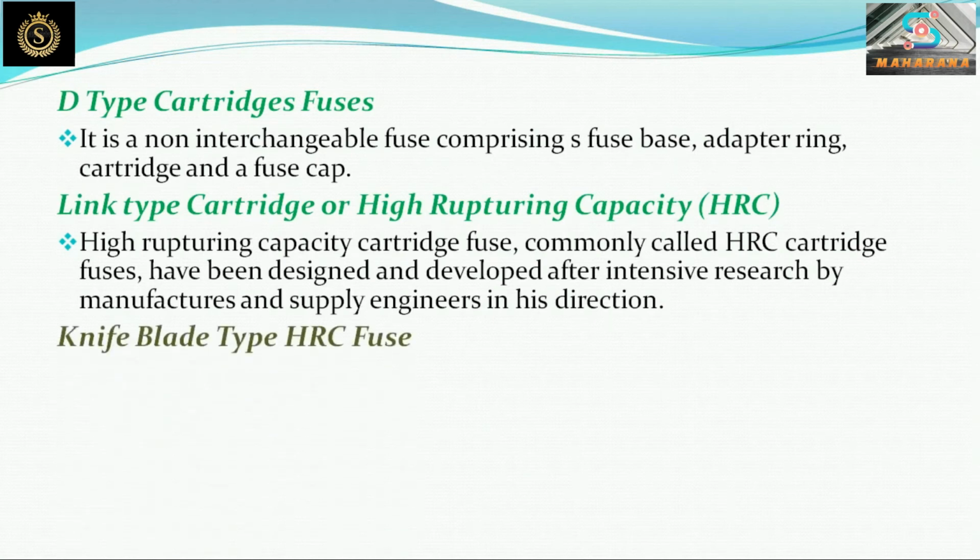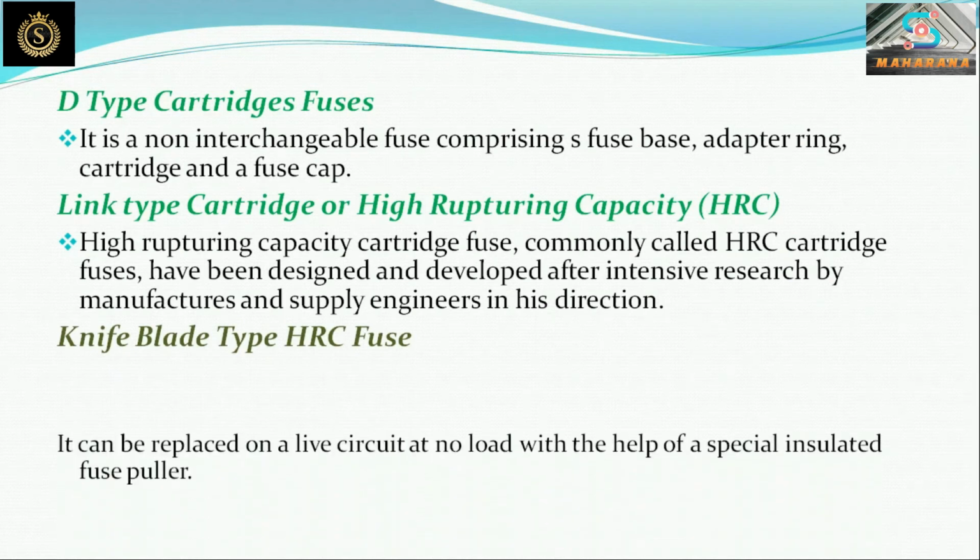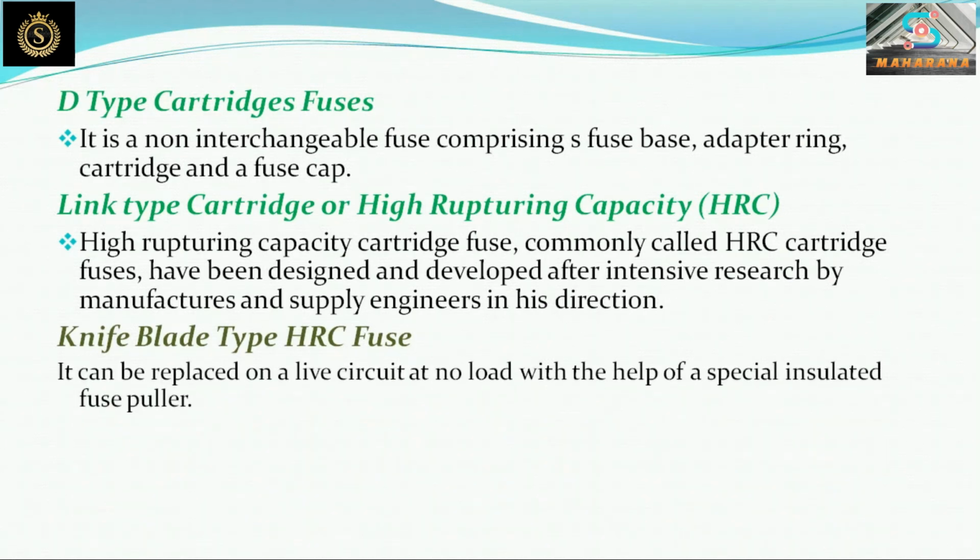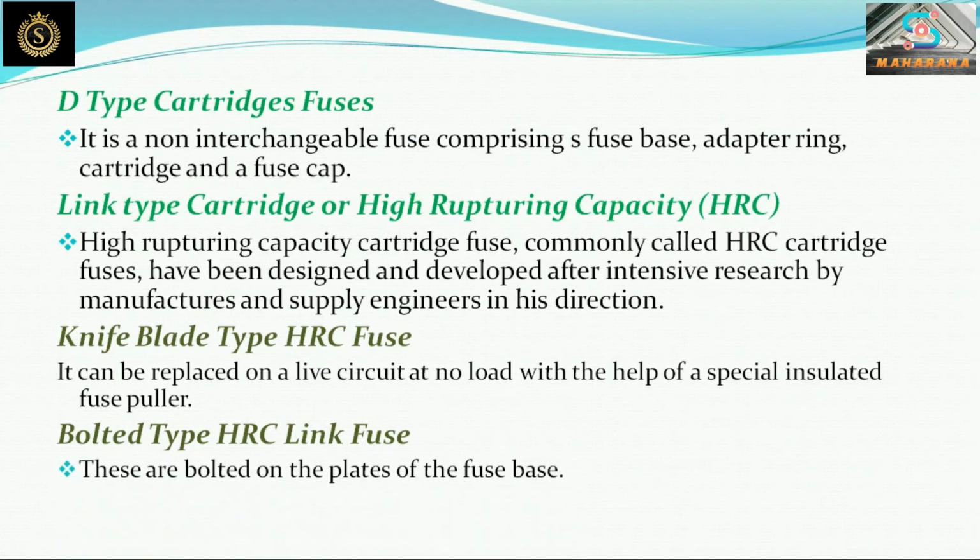Knife blade type HRC fuse. It can be replaced on a live circuit at no load with the help of a special insulated fuse puller. Bolted type HRC link fuse. These are bolted on the plates of the fuse base.